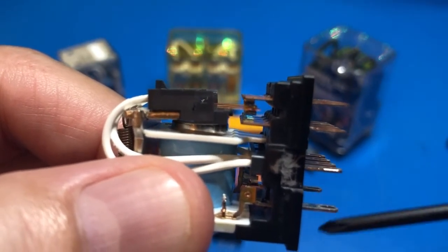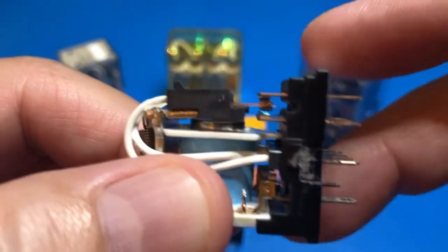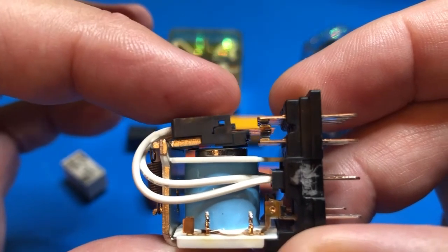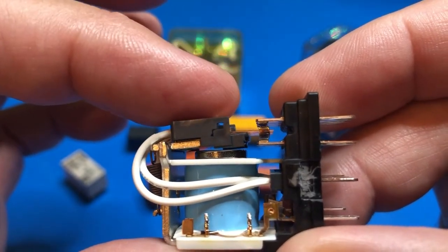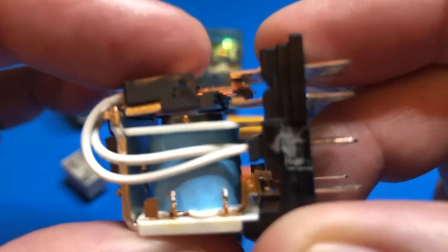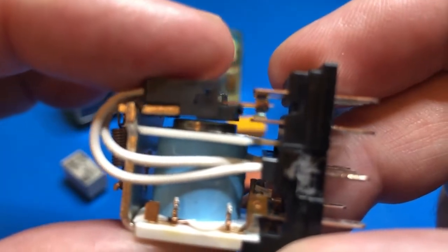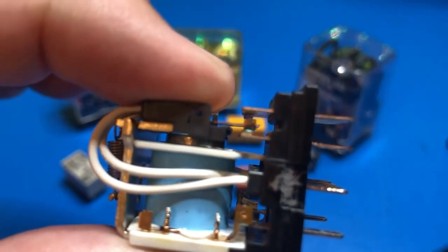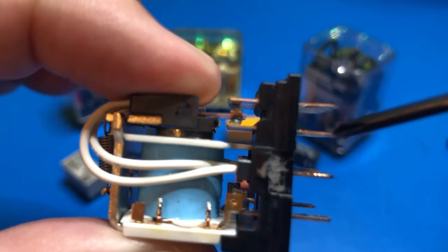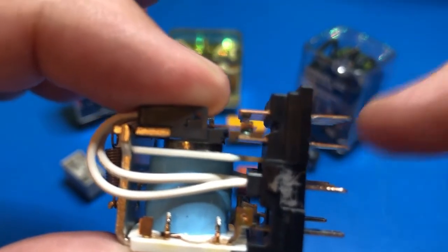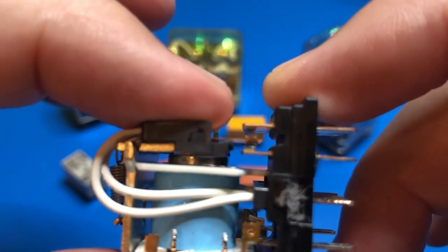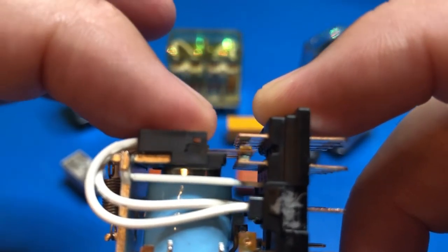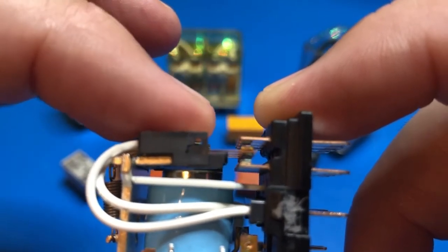Now, if we send an electrical signal here, this one is going to act like a magnet, and it's going to attract this armature, and it's going to bring the contact that is in the middle to the other side. See those contacts? When the winding is activated, it's going to move this way. Now we are closing this one and this one. And that's how an electromechanical switch works, by sending a control signal and moving the contacts from one side to another.